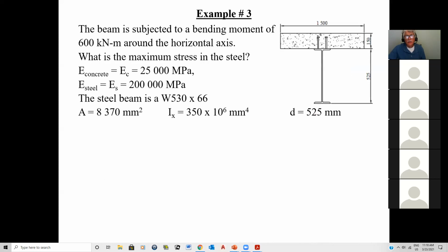Here's a typical situation that you have when you're designing a highway overpass. In a highway overpass, you use steel girders, and you put a concrete deck on top of your steel girders to create the roadway. You're going to want the concrete to work compositely with your steel. Next time you see an overpass being built and you can see the girders, you're going to see the steel girder, and on top of those steel girders, you're going to see